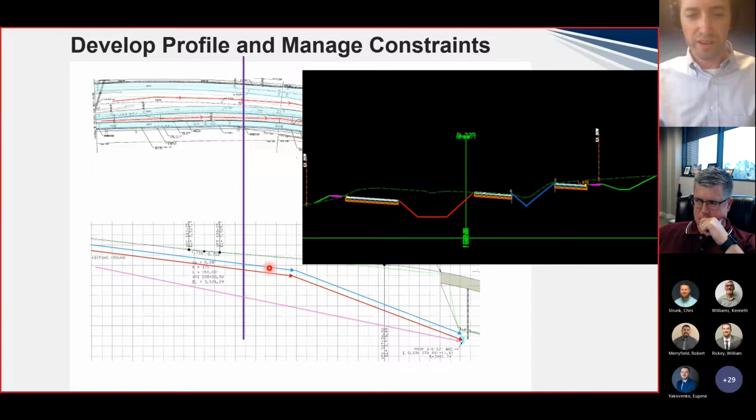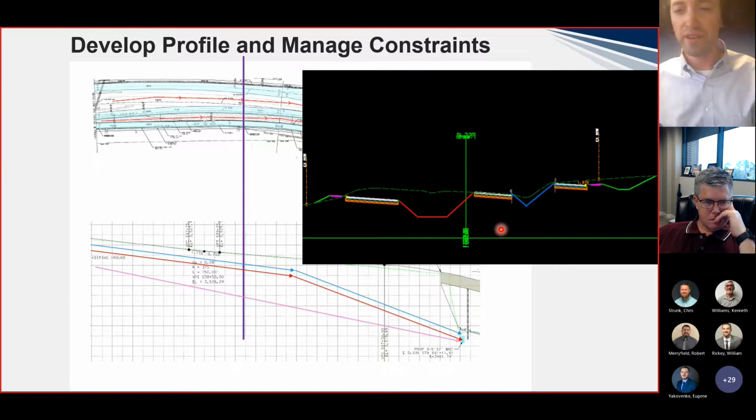So we've raised this one up from down here to up here. Now we have a large elevation difference between the northbound frontage road and the main lanes. So we do have pretty steep slopes, and this area and design ended up needing concrete riprap, but it works, and we got some guard fence to protect drivers, and it drains to the outlet that we want it to.